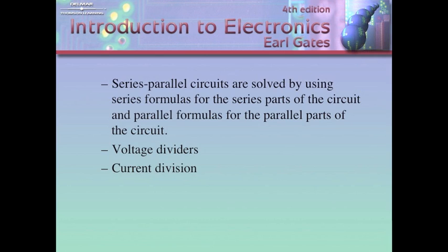Okay? So what you want to do when you're developing a circuit like this is, this resistor right here starts the voltage division process, this divides one, this divides more of the voltage. This is called our bleeder resistor, the resistor between node C and D. In order for this circuit to operate efficiently, we need to have 1/10 of the total load current flowing through it.